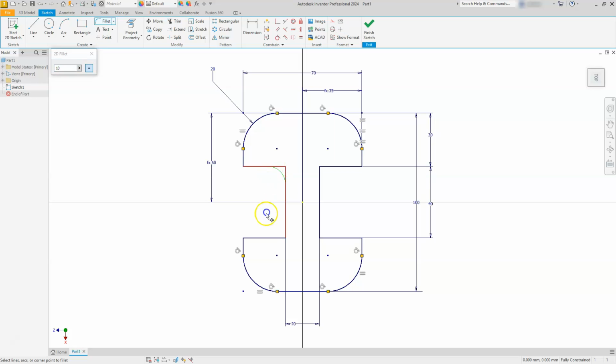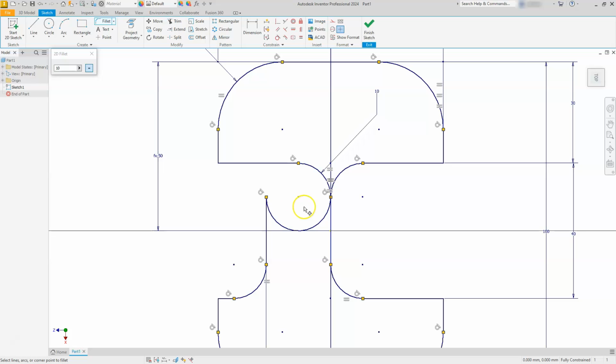And I'll start working on my inside. Now I know this is one of the things I was kind of worried about when I created this: when I start putting these fillets on, it tries to keep these two lines equal. So that's the one that's driving this crazy, the two equal constraints. You can see that I got something extra going on here.